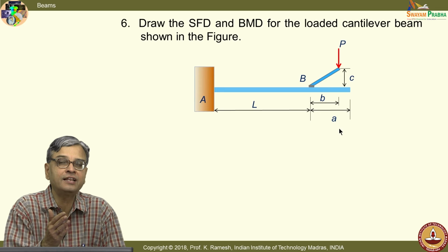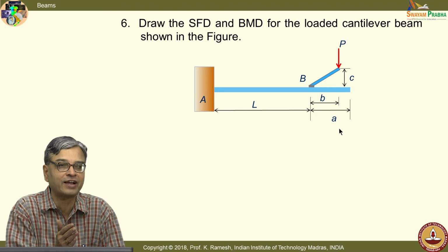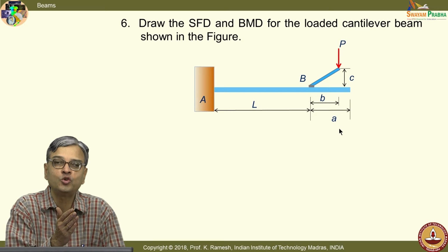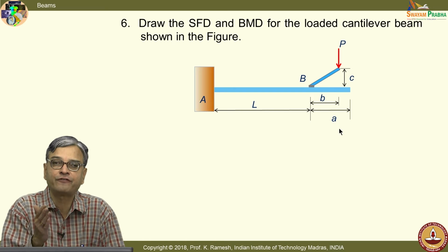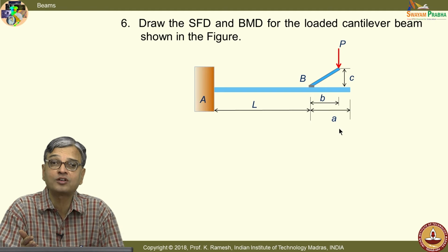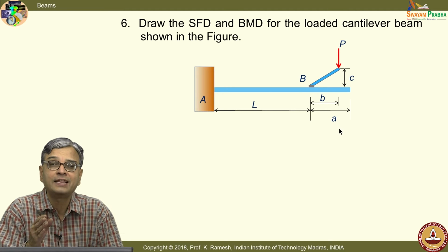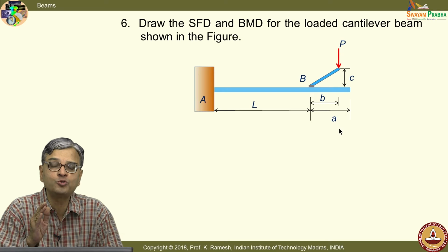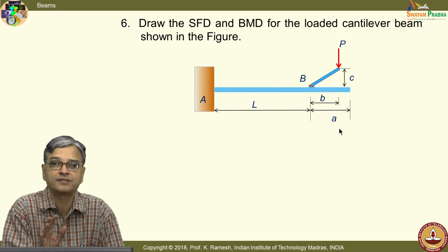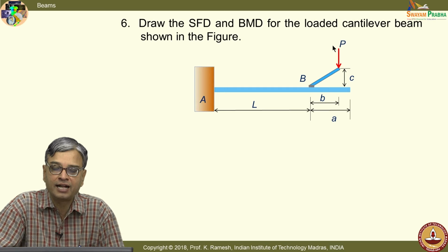You have already seen how to translate a force from one line of action to another line of action, the resolution of a force into a force and a couple. You have to apply that concept here. While we discussed that, we said the external effect produced by the original force needs to be preserved. So, now the first step is that I have to translate this force to the point B.